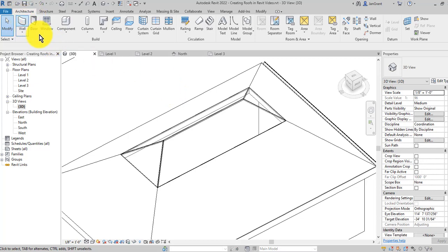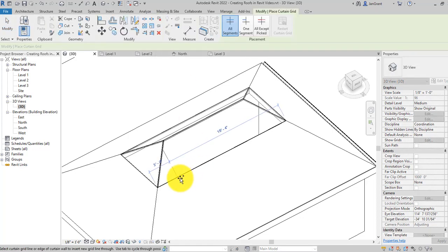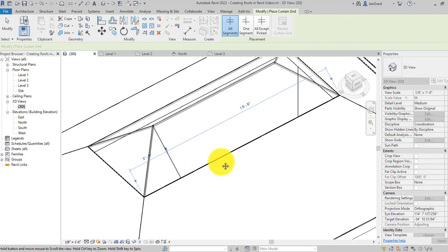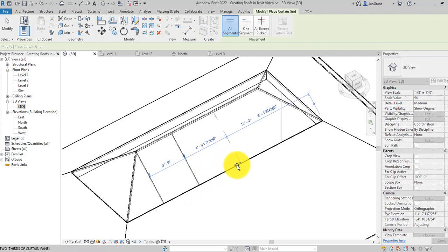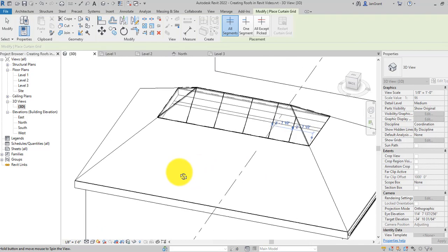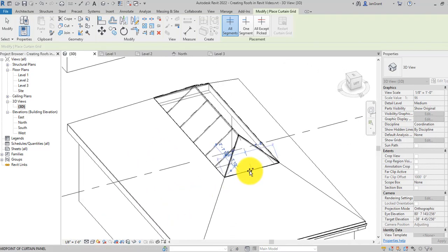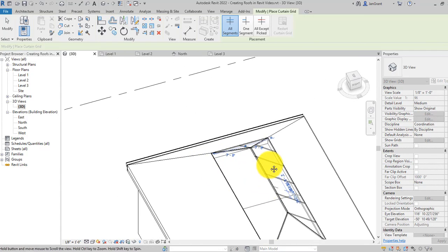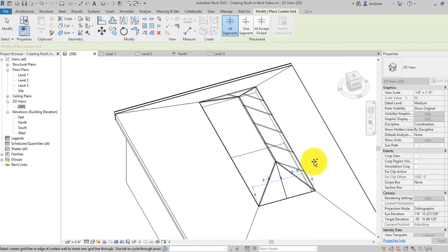But guys, in the architecture tab, click on curtain grid, and see, this is where you can decide where to put these cuts. So, thinking about glass, maybe you want it to cut along here at a specific distance. I know that I'm just randomly picking cut lines, but we want to think this out a little bit more when we're creating these cut lines around both sides. And I think what I'm going to do is modify it. So I'm going to escape out of this.